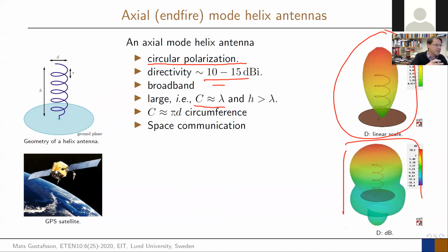So that means that this one is almost a loop antenna that sits there. You can think about it as you remember when you had the loop that goes around, it radiated from there and from there. So two dipoles that sit slightly shifted. That is how the loop radiates. What does that mean for your helix? Then you can say I have one radiation there, and then you can move around to the other one, you have one there. And if you look in height, they are slightly separated.